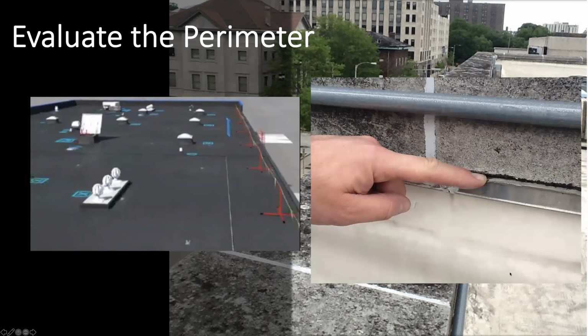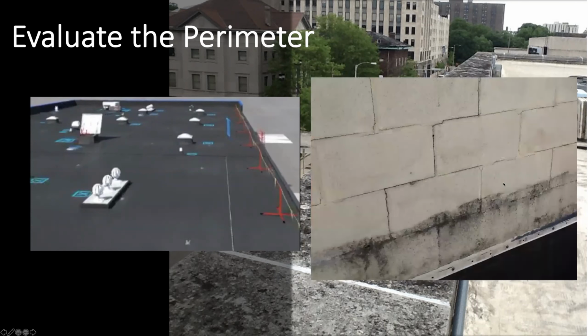Another maintenance type item is where roofing flashings are terminated on your wall, and they typically use a bead of construction type sealant there, and that fails. Over time, the UV breaks that down. That needs to be looked at annually and fixed as necessary.